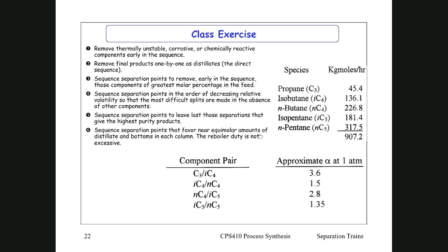You might have seen pictures of distillation columns where the bottom part of the column is very broad, and the top half is a thin thing sticking out the top, and the feed is where those two diameters meet. Of course, that also adds to the cost of the column to have to do the diameter. So that's pretty much where heuristic 6 comes from.